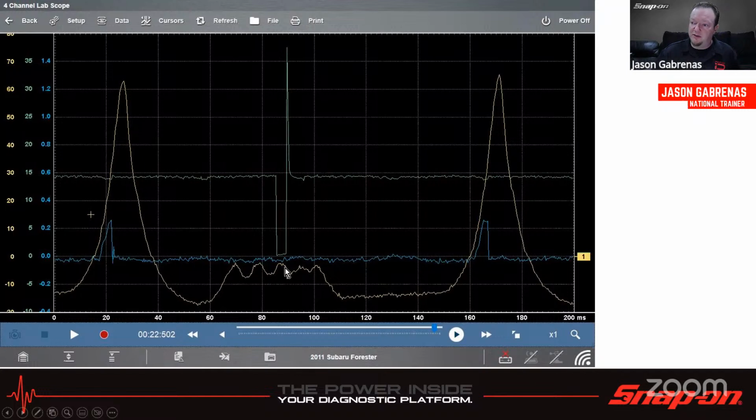I see the other cylinders, actually. You can kind of see some crossplay going on. And then we have where the injector would spray, and then the intake valves open right as soon as the injector sprays. So you can see how the pattern changed. Get a little bit of swirl going on in there. And of course, there's valve overlap. And then it comes down, and then we have our vacuum pocket, and then it compresses again, and so on and so forth. And as the engine runs, that's how it runs.